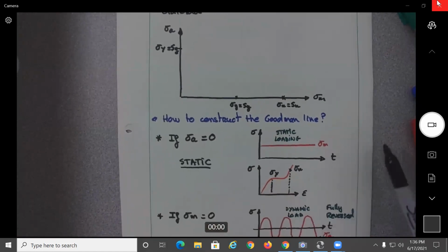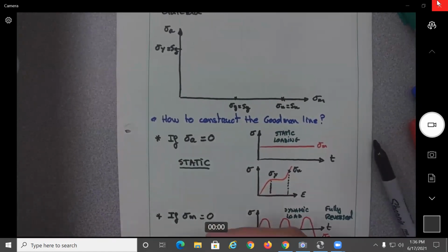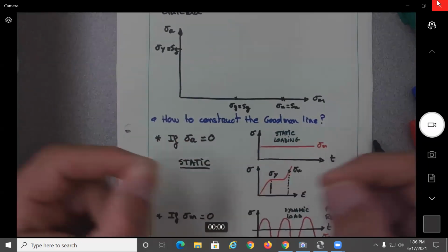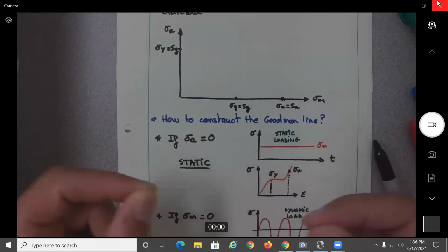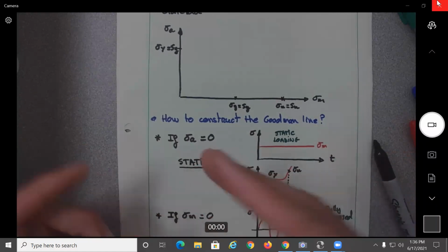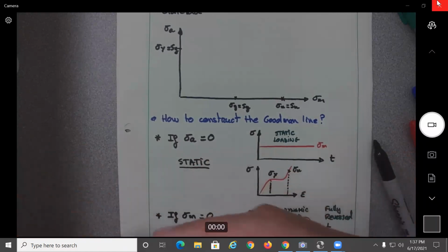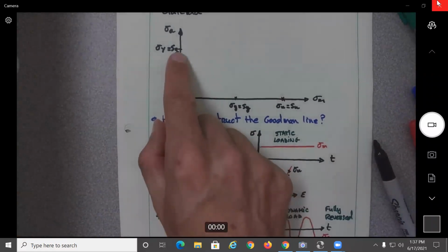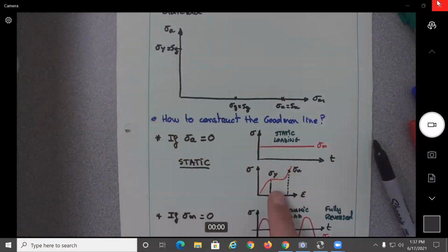You have a structure, a piece that you put into a machine and you start shaking it, okay, over time. And you leave it over time, you can find out after a certain number of cycles of doing the same thing, the structure is going to fail, no? Okay, and that value is probably going to be lower than the yield value. Does that make sense or not?